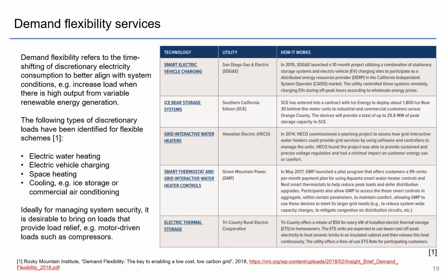But I guess for managing system security, it would be desirable to bring on loads that provide load relief, so motor-driven loads, such as compressors. I mean, electric water heating and space heating probably wouldn't really help that much in terms of providing that load relief.